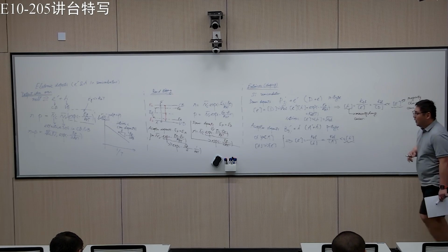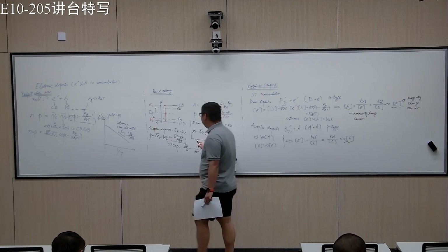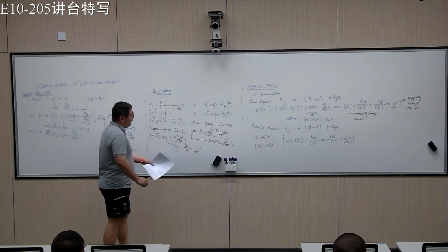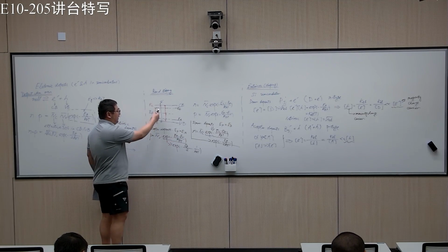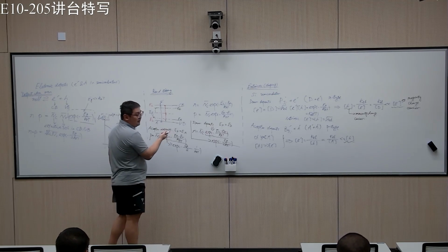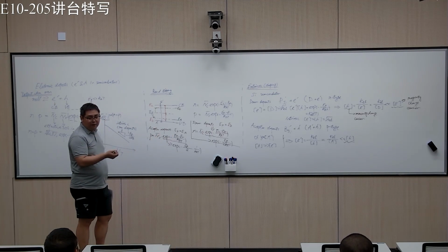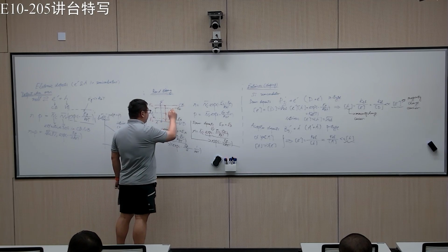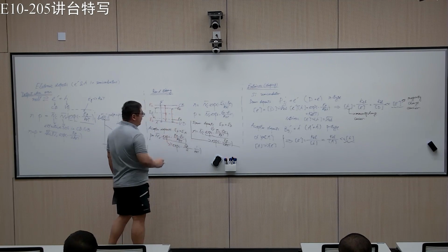Okay. So we can also see that if we follow the band diagram, for example, if we have donor dopants, the formula is up here, then of course the holes become minority charge carrier simply because this distance is very large, right?